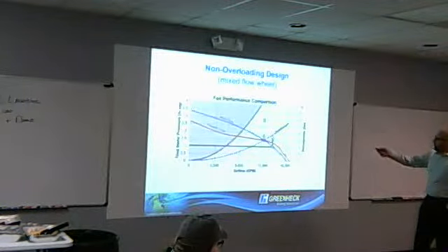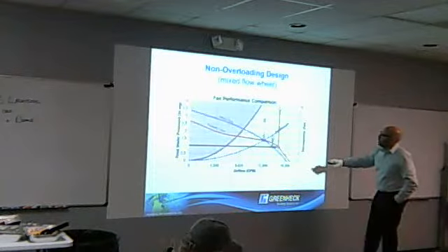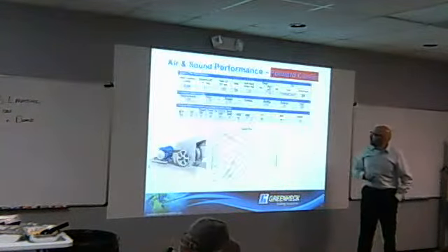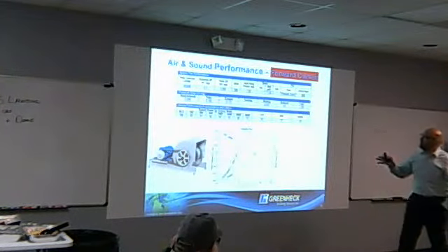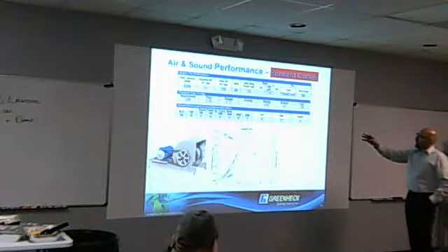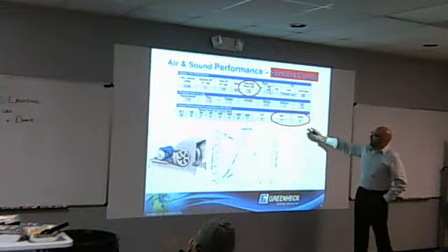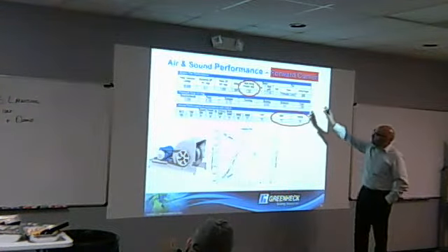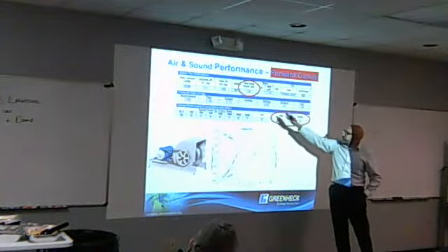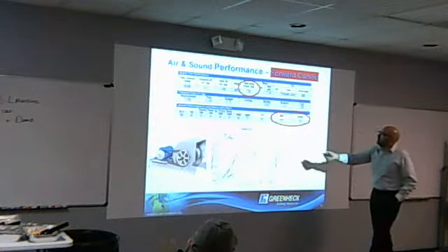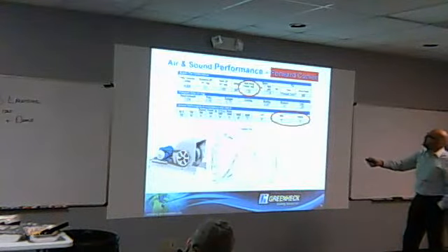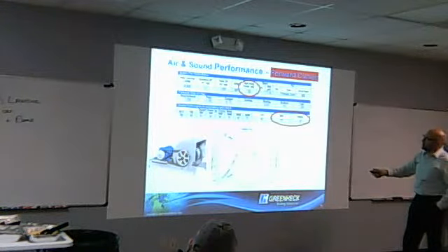So we went through this already in terms of the operating points. If we step back and look at a selection and begin to watch the operating power and the sound levels of these different arrangements. In the forward curve, 7.26, this is 10,000 CFM at 0.5 inches, 726, 79 dBA.